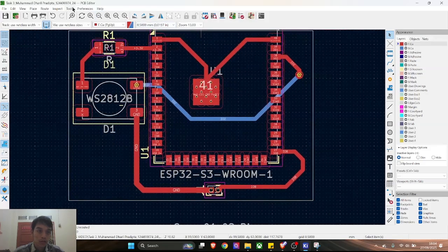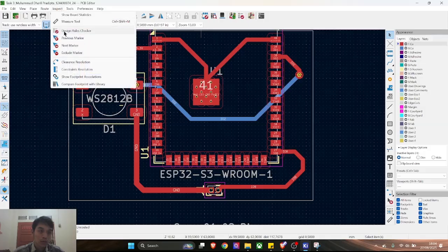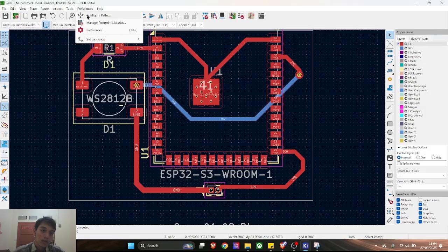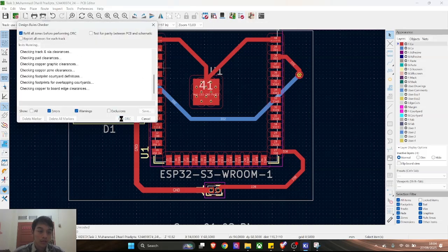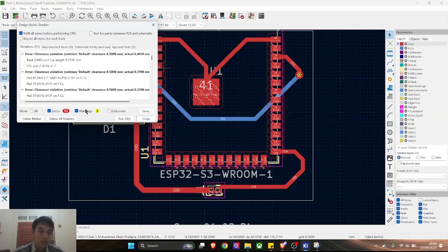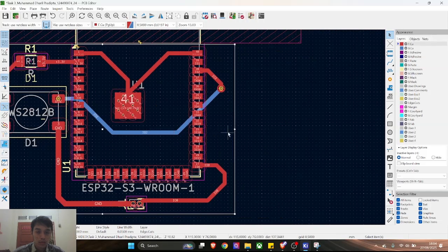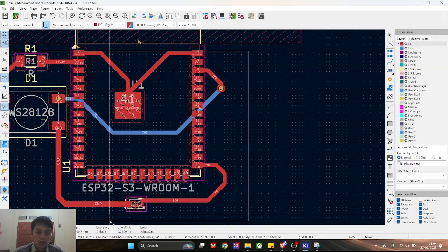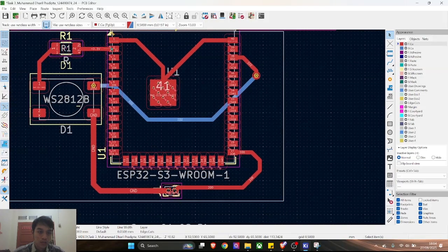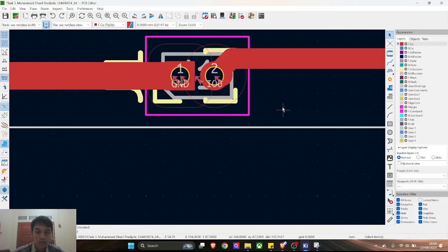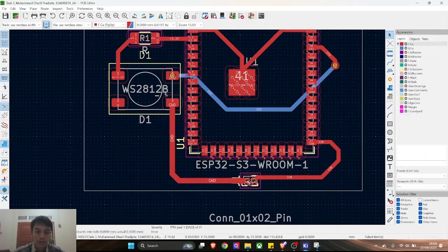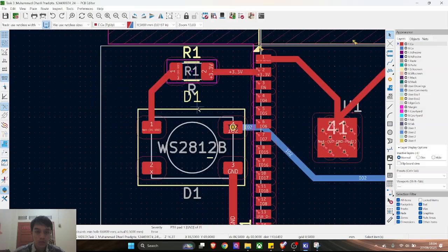So let's check the inspect. Here on the DRC there are 53. What's the warning? Clearance. Okay. Let's try to make it a bit bigger. Oh, I see the problem. So we can neglect all these red lines. It should be fine. Here is a bit of trouble here. But we have no problem here from the current design.